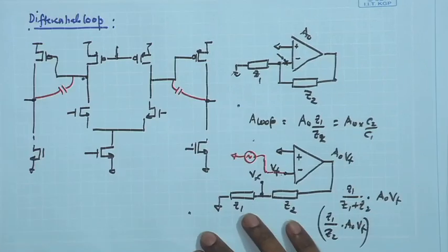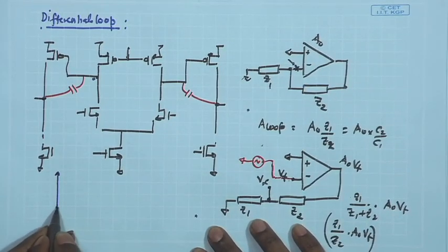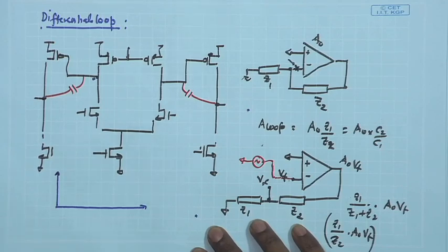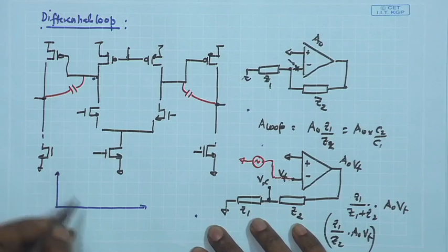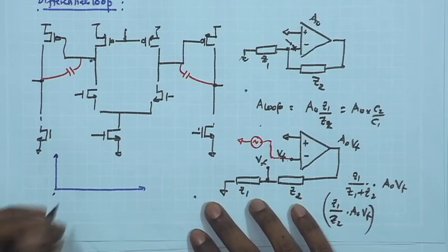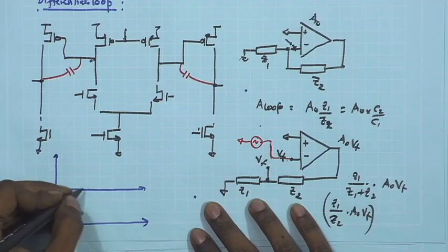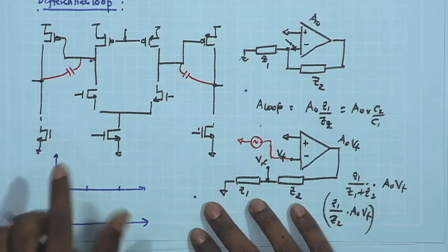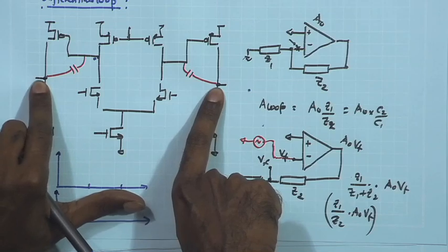And if I look at the Bode plot, for example, for the magnitude and the phase response, what we are seeing is that the poles in these two cases are almost remaining similar, right. So, if I look at these two cases, for the common mode feedback loop, what we are saying is the critical poles are at this point and this point, and therefore,